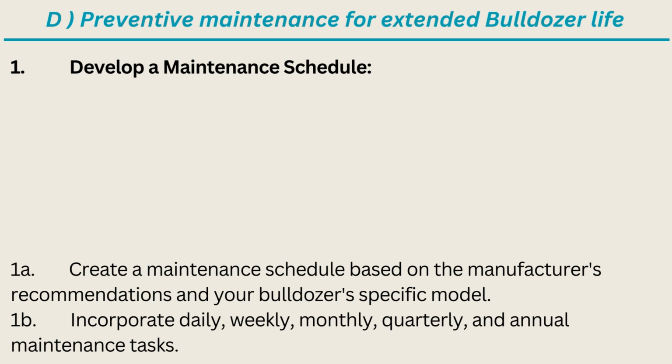1. Develop a maintenance schedule. 1A. Create a maintenance schedule based on the manufacturer's recommendations and your bulldozer's specific model. 1B. Incorporate daily, weekly, monthly, quarterly, and annual maintenance tasks.